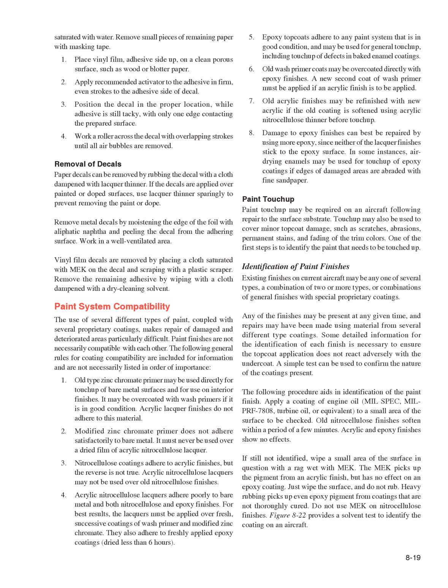In some instances, air drying enamels may be used for touch-up of epoxy coatings if edges of damaged areas are abraded with fine sandpaper. Paint touch-up may be required on an aircraft following repair to the surface substrate. Touch-up may also be used to cover minor topcoat damage, such as scratches, abrasions, permanent stains, and fading of the trim colors. One of the first steps is to identify the paint that needs to be touched up.